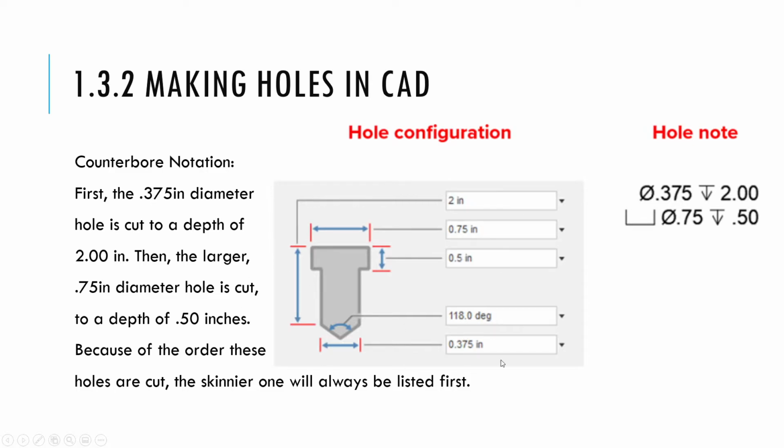If you look at here, this is just sort of like a paragraph I wrote based on these notes right here. You'll see that there are two places where it's measured across, and this one here measures the diameter across the majority of the hole as it goes down. That's 3/8 of an inch. This one across the top here measures the top of the bore feature. And these two vertical measurements tell you depths. So this depth right here, down to the bottom of the hole, is 2 inches, and the depth of the bore feature is 1/2 inch.